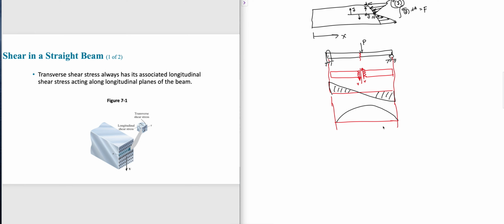Something close to that, isn't it? That means where is the shear force maximum? It is maximum here, at the leftmost or the rightmost edge. Would you agree to that, for that given loading? So in the previous chapter, we already discussed the maximum bending moment, exactly at the center in this type of loading. What happened to normal stress? What happened to sigma? That's what we found out.